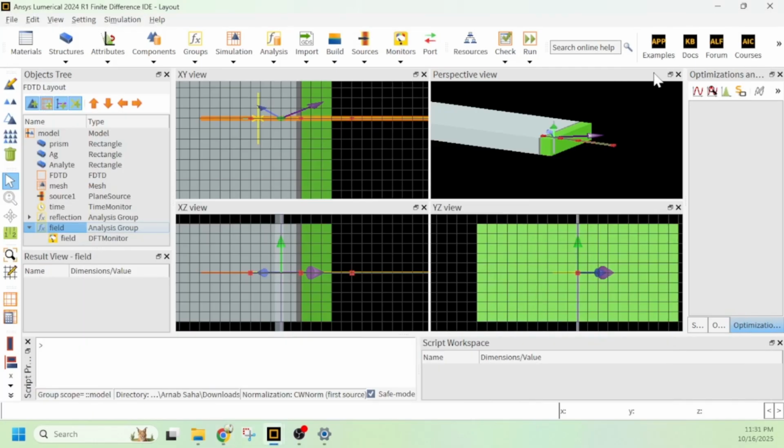a variable parameter for angle sweep, that you need to define the angle can vary from 40 to 60. So for this you need to follow here, just here, that is this point, this is sweep, and I will create a sweep and just click here and you will get this button sweep. And now just here from the edit option I need to set this sweep. This is very crucial at this moment.